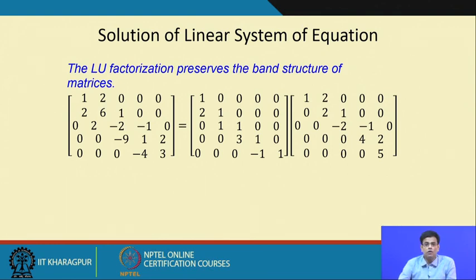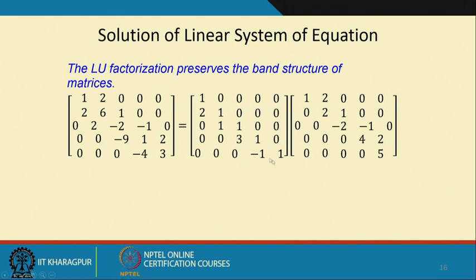This is very important because we will mostly be using banded matrices for structural analysis, since stiffness matrices, when assembled, will be in a band format. If we do the LU decomposition of a banded matrix, its banded form is preserved in the L and U matrices.